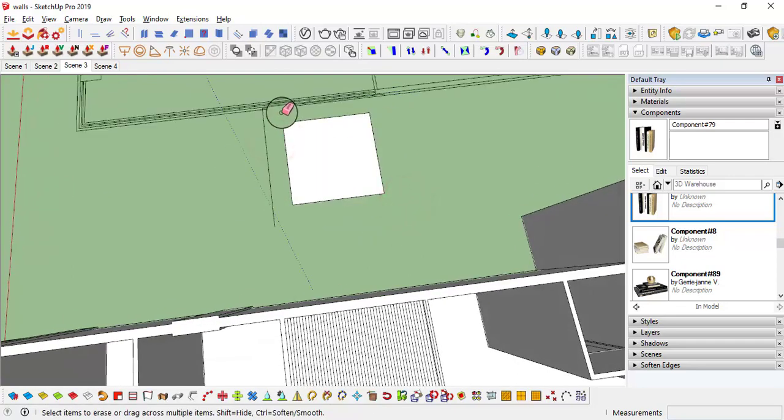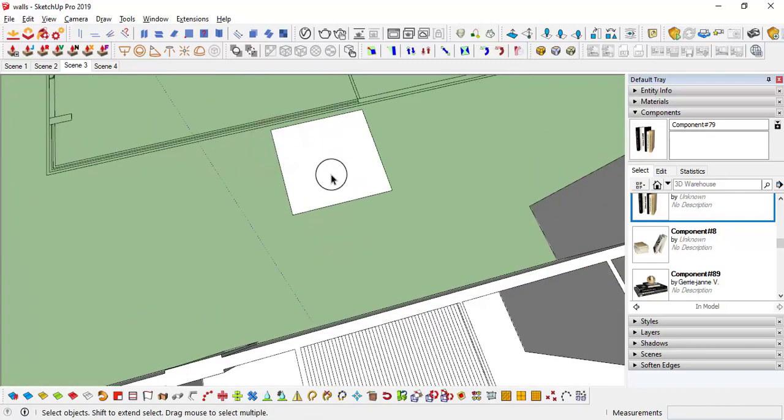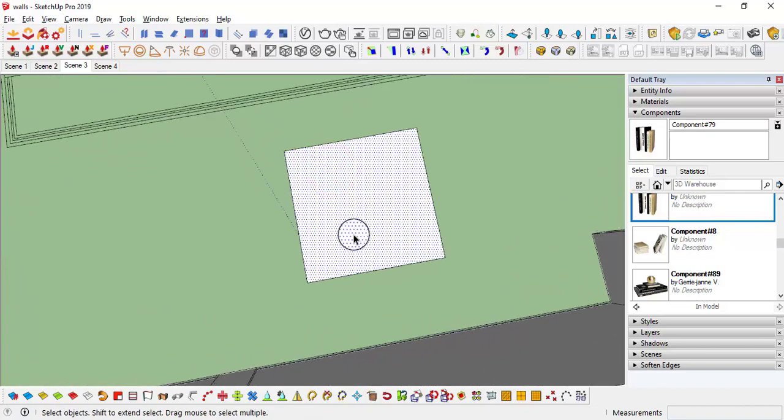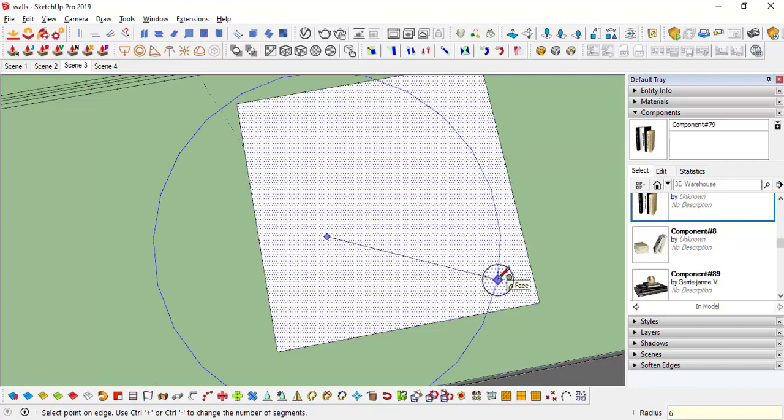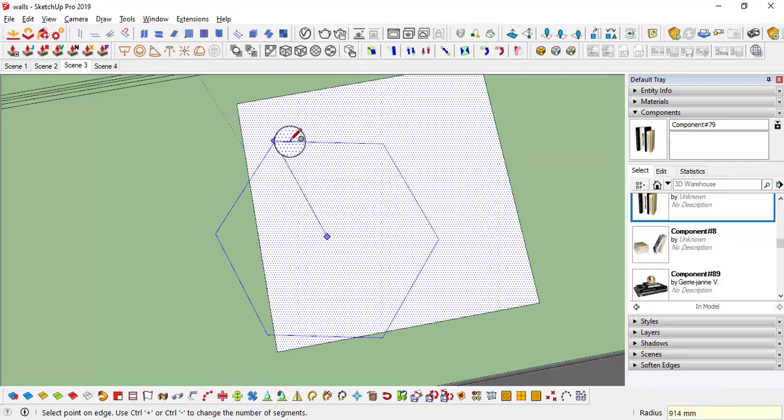Okay, Control Z. First of all, how can you make the hexagon very easily with the circle? While drawing the circle, assign 6 sides, yes, enter. Now it is a hexagon, right? And show this direction. How much do you need? Like 6 inches. If you say 6 inches radius, probably it is 1 foot. So I will say 4 inches. 4 inch, click enter.